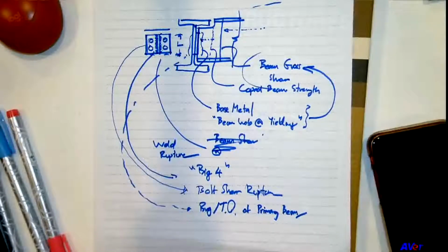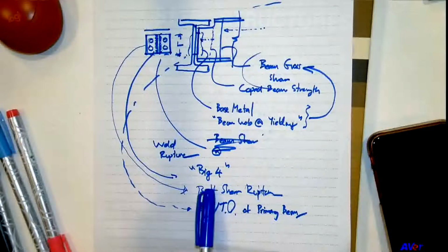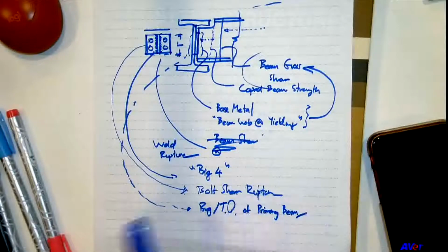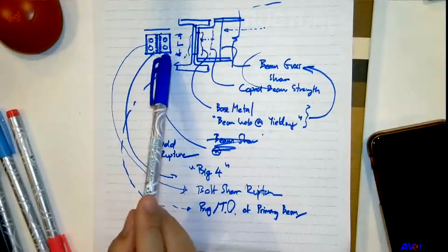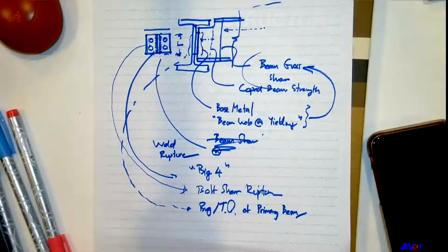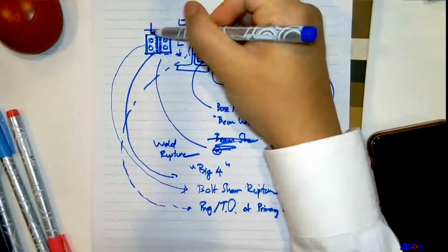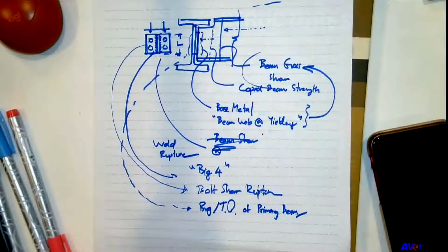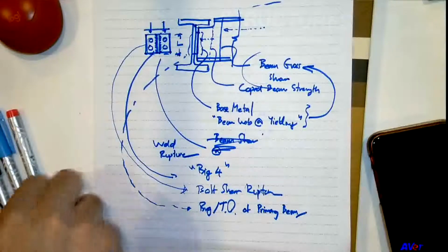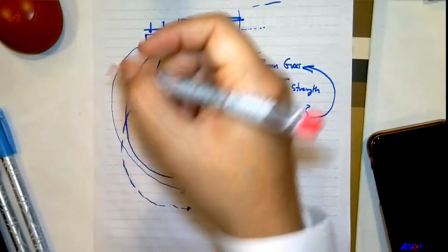L. And then the plate, shear yielding, shear rupture, 0.6 Fy multiplied by this length, and then multiplied by the thickness of the plate. Keep in mind that the shear yielding and shear rupture should occur on both sides, right? So you have two planes in this case. And then the block shear, for the block shear to occur, is this piece.